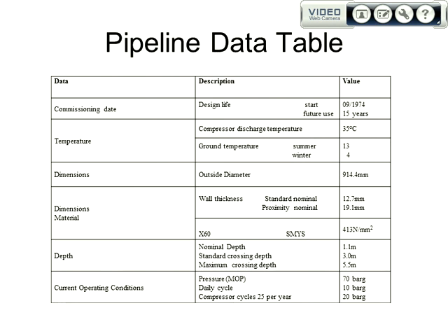Sorry, we missed regarding the daily cycling, 10 bar. So what you need to do is find out what stress a 10 bar pressure is going to introduce in the pipeline. That's the daily cyclic stress range. So it's going to see that stress multiplied by 365 days each year, multiplied by however many years it's been in operation. Then you need to do exactly the same thing for the compressor cycles, but that's on a yearly basis. And the formulae for how to do it are in the design section of the design code that I've given you.